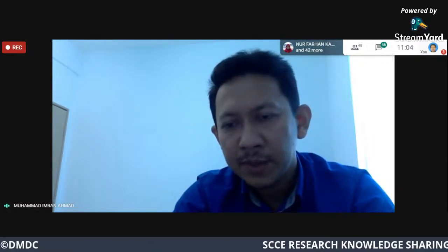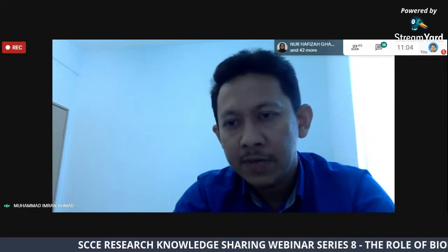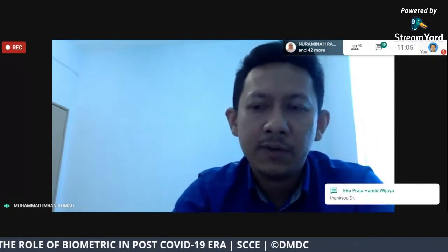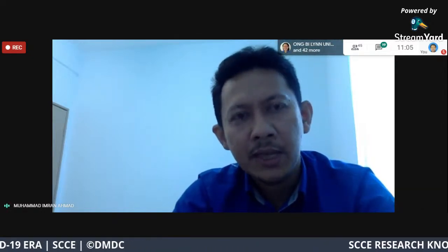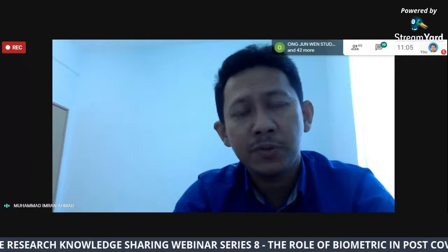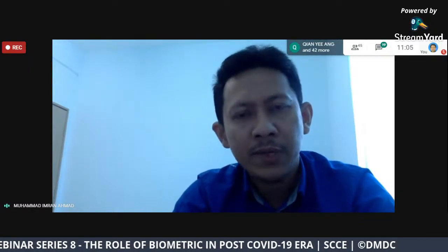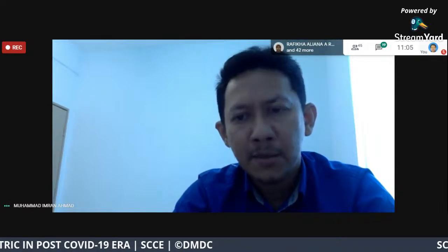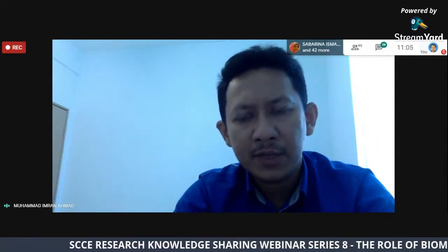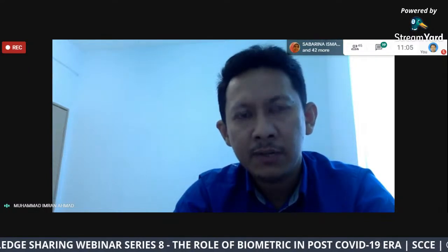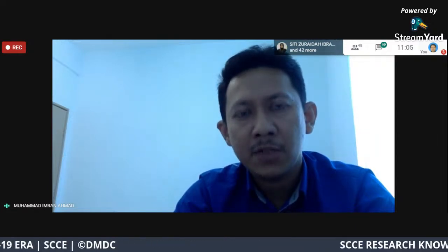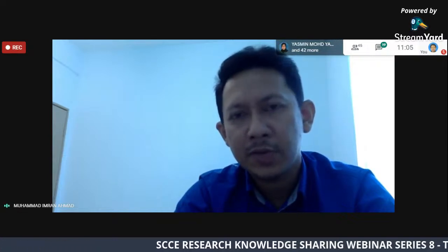And we have another question by Suhaizal. How do the consistency and stability of the light source during each photo session and throughout the process affect accuracy? Okay. The light source is considered one of the variations in facial recognition. Let's say you put your camera in front of the sunlight, and then tomorrow you take it again in the room, the system will fail. So we need to have a very consistent light source for the recognition purpose. And normally for the setting of facial recognition, we try to use LED with our camera, so we can have a constant level of light for training and also for testing purposes.